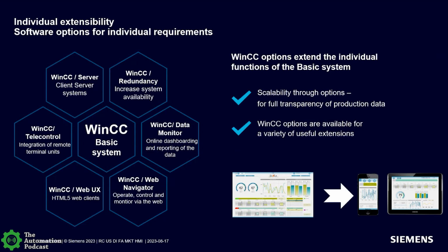WinCC Data Monitor gives you the ability to do some management type dashboards there to report the data. You can create it in the engineering world, or you can create it on the fly in the runtime world, where you can do tables, charts, graphs, however you want to look at the data, and specify a time span. If you want to look at some pictures, they're just still graphics because it doesn't provide live picture updates, but it does give you the ability to bring live data into a dashboard setup there.